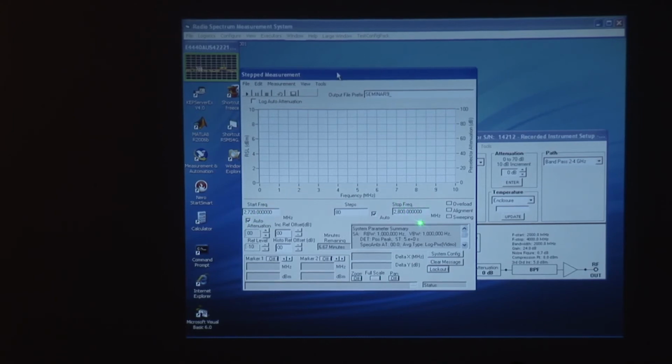Well, the difference between these two numbers is 80 megahertz. So if we're in a 1 megahertz bandwidth for the measurement, and we're going to go through 80 megahertz of spectrum, we need 80 steps. The math works out rather nicely on this.